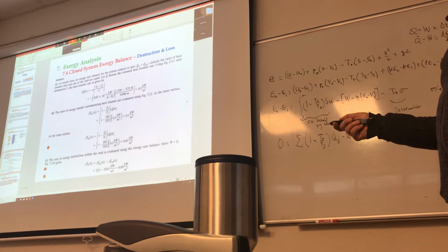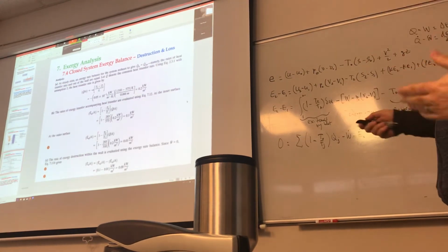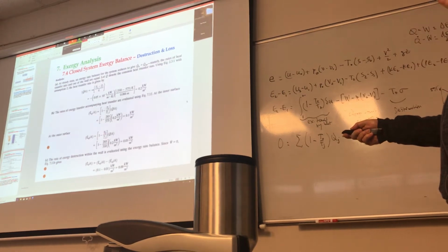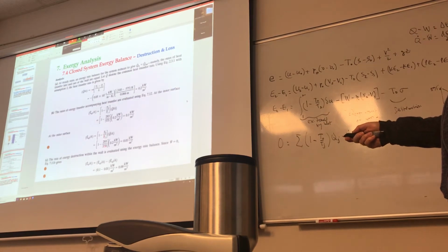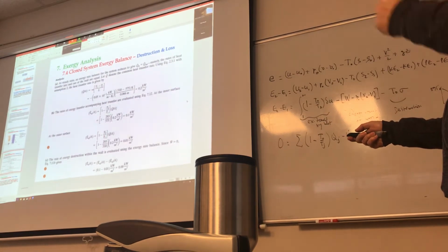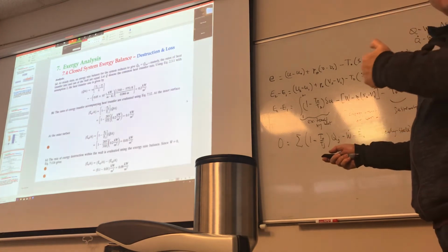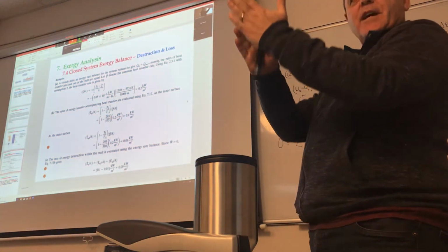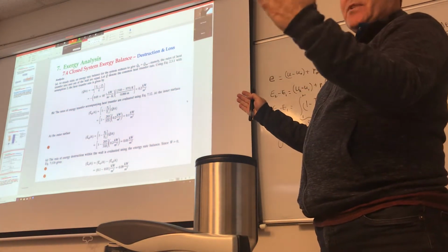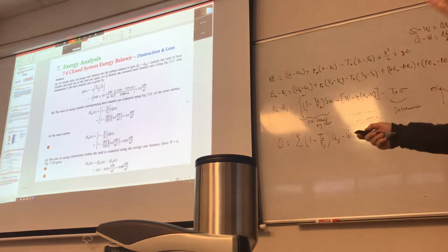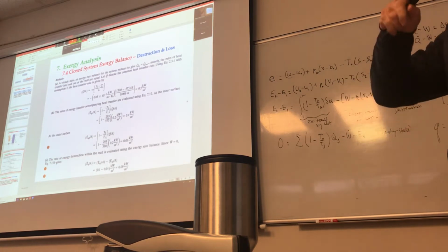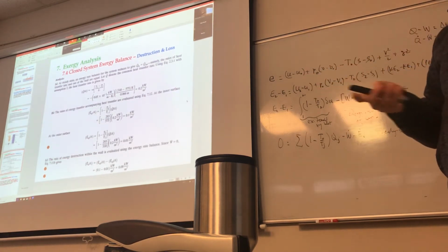How much is transferred by the second surface, the outgoing surface? The equation is exactly the same. T naught is the same. What has changed is that the temperature has gone down to T2, which is 310, and the exergy crossing that boundary is only 0.01. So you're coming in at 0.1, and you're leaving at 0.01. That means the difference got destroyed within, through irreversibility of the system.